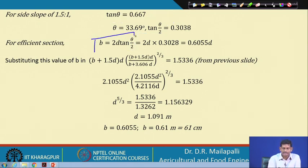We discussed this in the previous lectures when we were talking about the most economical channel depth and width relationship. So, that is 2D into tan theta by 2, 0.3028. So, that will be 0.6055 D, and substituting this value of B in this equation.